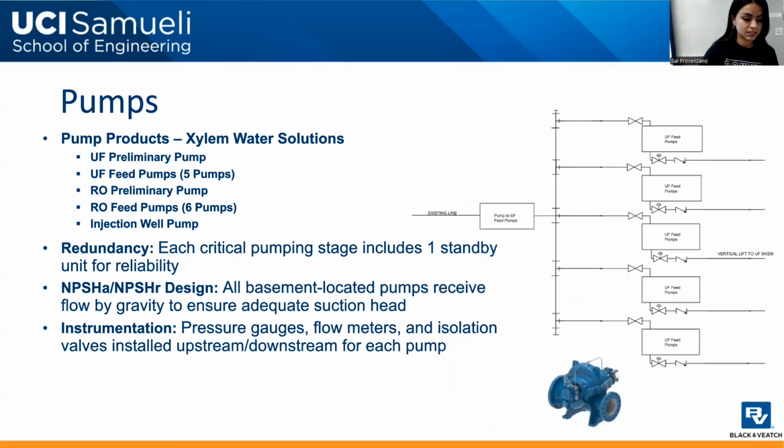Thank you, Giselle. I'm going to be discussing the pumps, and we settled with the Xylem water solution, which will provide the UF feed pumps as well as the preliminary pumps, the RO preliminary feed pumps, as well as the injection well pumps. We added redundancy to each pump station just to account for maintenance. We calculated the net positive suction head available and made sure that it was greater than the required for design purposes. And for the instrumentation, we made sure that pressure gauges, flow meters, and isolation valves are installed upstream and downstream for each pump.